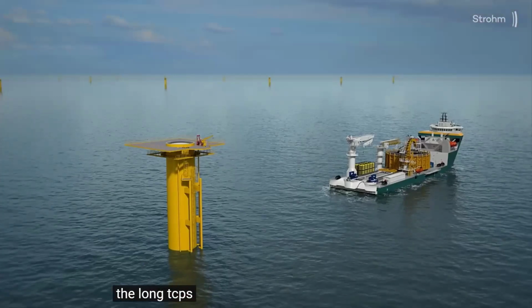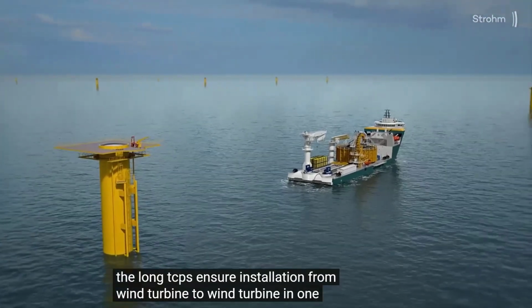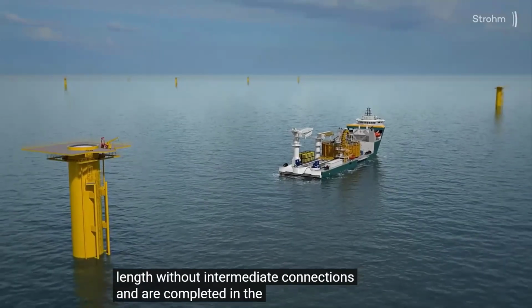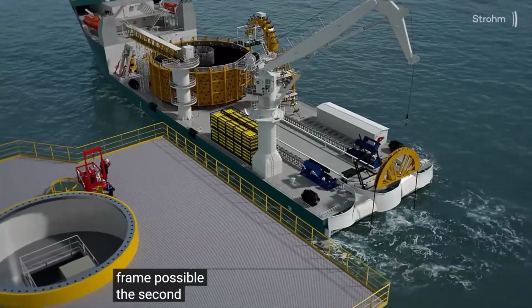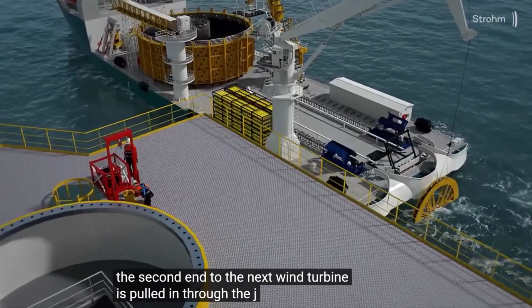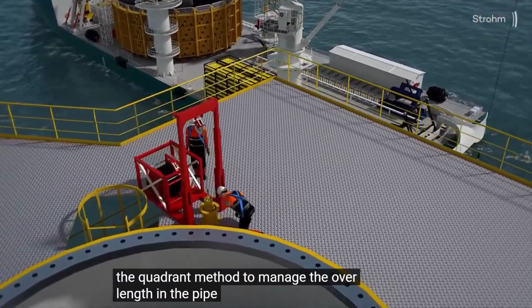The long TCPs ensure installation from wind turbine to wind turbine in one length without intermediate connections and are completed in the shortest time frame possible. The second end to the next wind turbine is pulled in through the J-tube using the quadrant method to manage the overlength in the pipe.